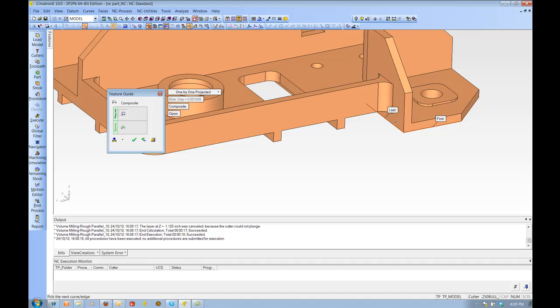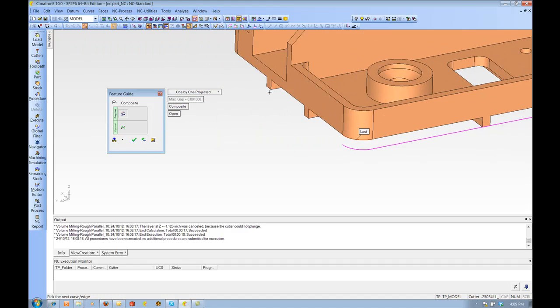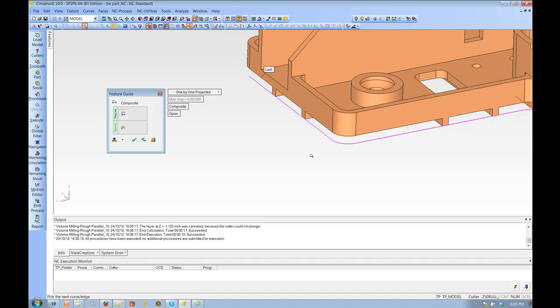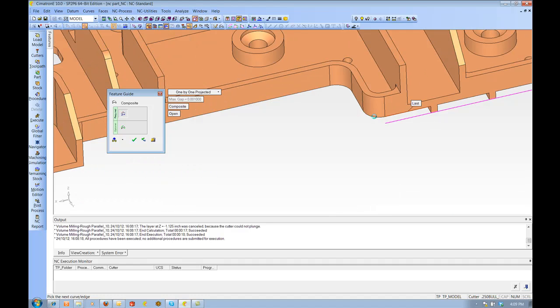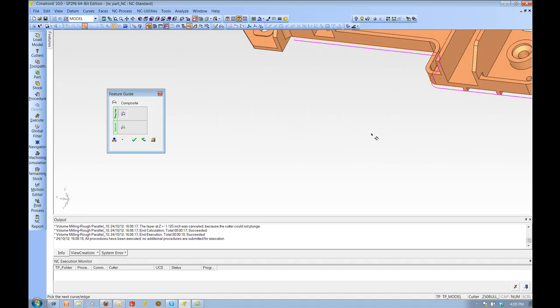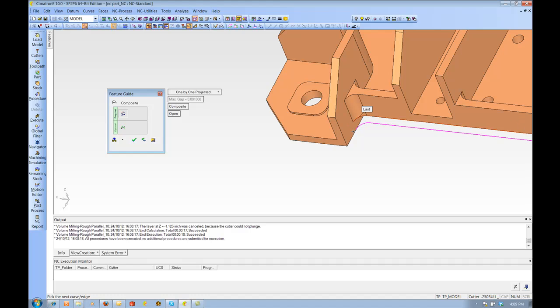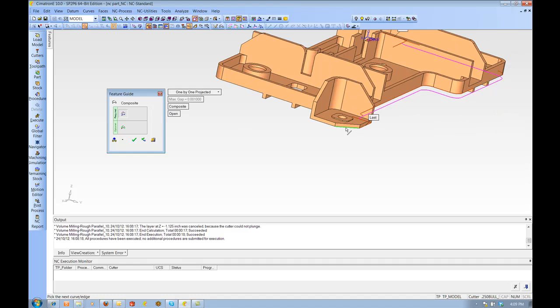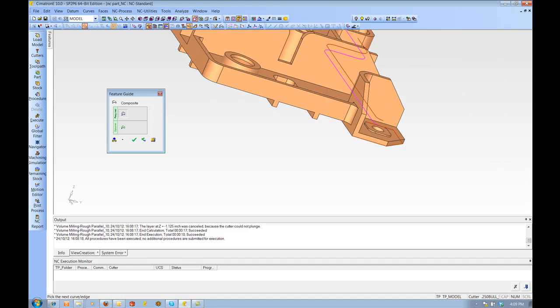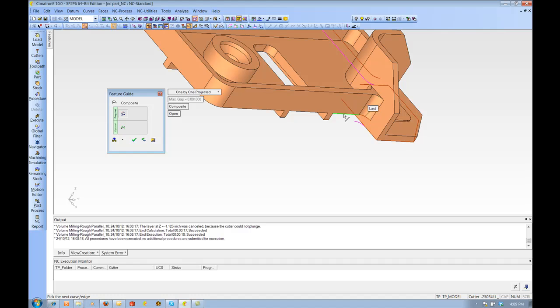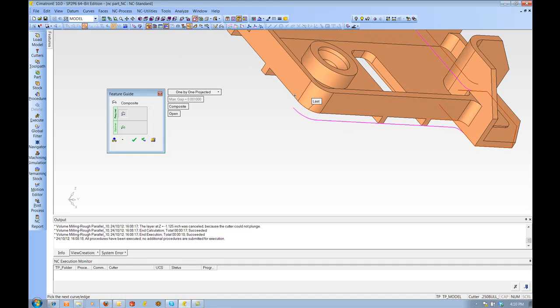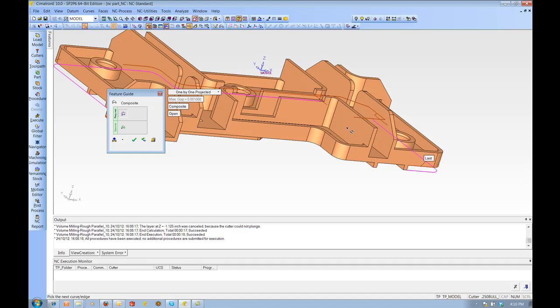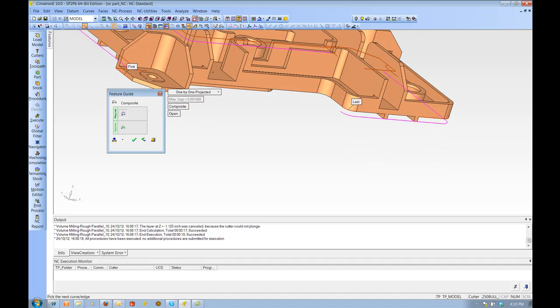And now we're going to do the outside perimeter. Now as I chain this, you'll see that I'm picking different Z levels, but it's all being projected down to the level of my very first pick. And it's even doing trimming and extending as well. So it projects down and then it trims or extends in order to keep a nice closed contour that's very forgiving based on the different geometry along the top.